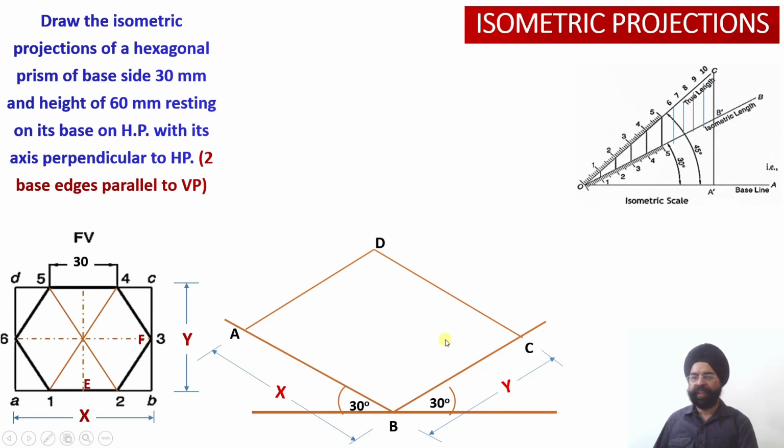But before I start with that, I have to draw the axis point. So please check, from point A, I measure the distance E, and then this center line will be drawn. Similarly, from B, I measure this distance F, and again a second center line will be drawn. So from B, I have measured the distance F as I move towards point C, and then another center line parallel to the x-axis has been drawn.